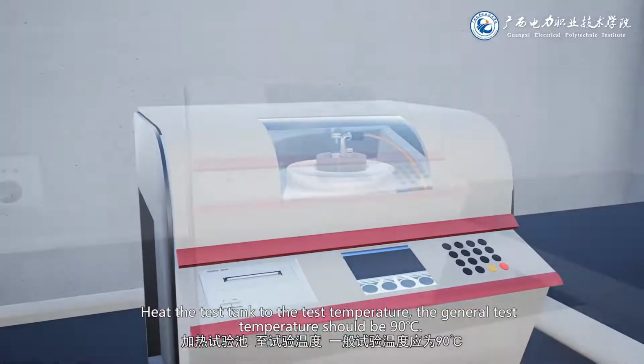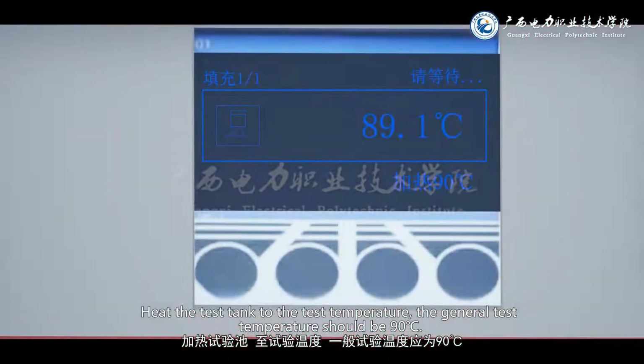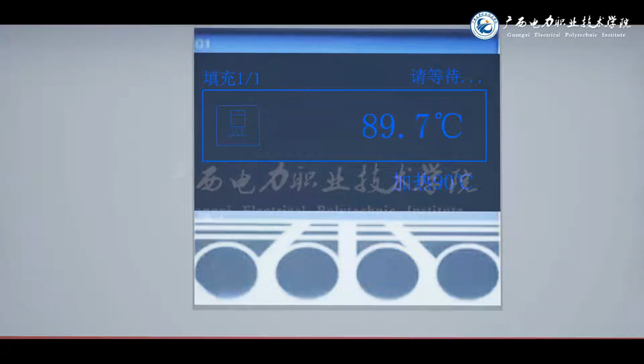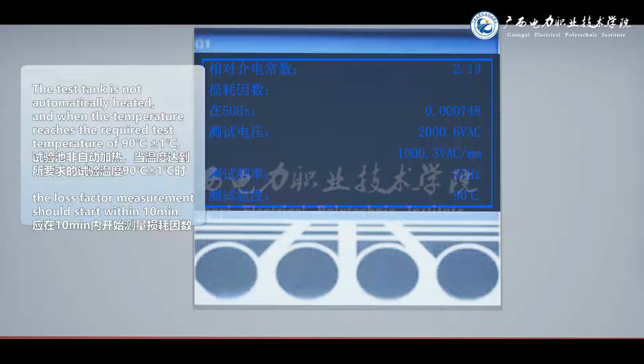Heat the test tank to the test temperature. The general test temperature should be 90 degrees Celsius. The resolution of the test temperature is within 0.25 degrees Celsius. The test cell is automatically heated, and when the temperature reaches plus or minus 1 degree Celsius of the required test temperature of 90 degrees Celsius, the loss factor measurement shall start within 10 minutes.